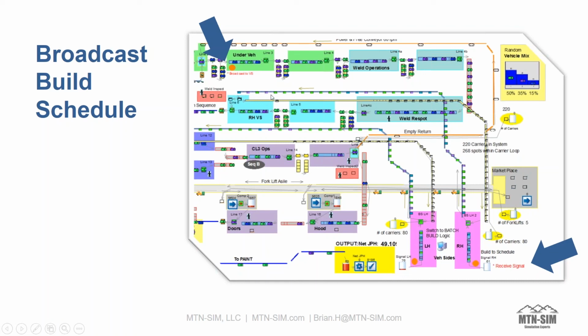So this represents where we send the broadcast. This is the subcomponent right here. This represents a body side, and we're actually receiving the signal. So this information says it's this type of vehicle. It might be a vehicle type 1 or a vehicle type 2 or a vehicle type 3, and it's going to build that respective vehicle type, place it into the power and free system. So we see that this is the loaded body side or vehicle side that's traveling to a particular point or rendezvous point where it's going to meet the main line and take that subassembly. And then the empty carrier returns on the empty return side.